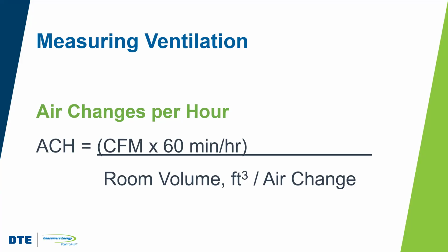A significant portion of that air is going to be recycled air or recirculated air, air that's been collected by the air distribution system and then taken back to the central equipment, the furnace, the air handler, what have you, and then reconditioned, cleaned, filtered, heated, and possibly humidified, or cooled and dehumidified, and then sent back to the various rooms of the house to do more work, picking up heat.